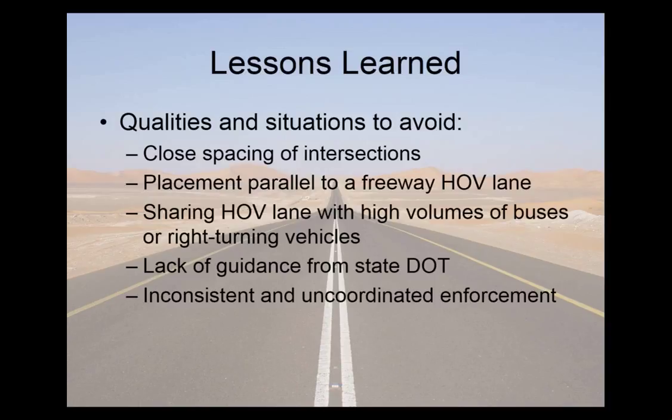HOV lanes should not be shared with high volumes of buses or right-turning vehicles, since this will undermine the travel time savings for HOV lanes. HOV lanes should be supported by the State Department of Transportation with design guidelines and regulations. And the enforcement should be consistent across the various places where it occurs.